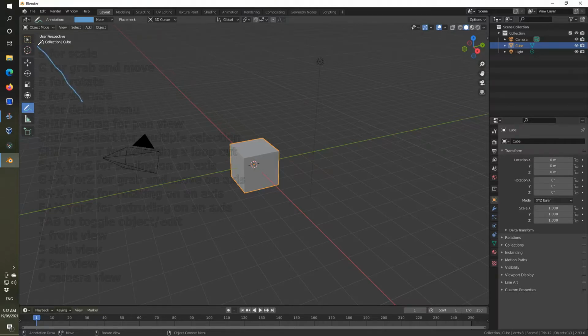Okay, we're back here now. First of all, troubleshooting. These are the settings. If it's not working for you, these settings you need to just go and check. Are you in object mode or edit mode? These ones here shouldn't be highlighted, not for this project.